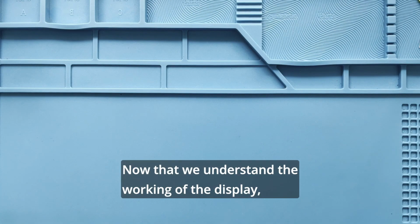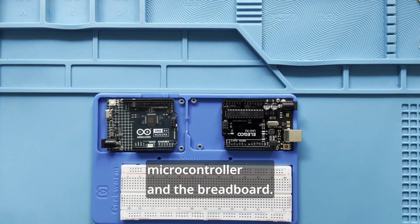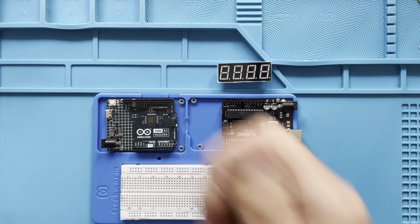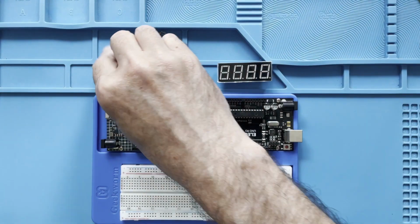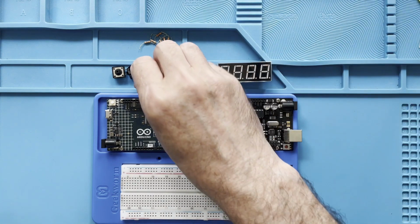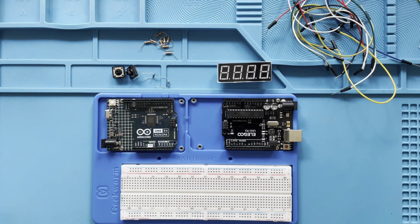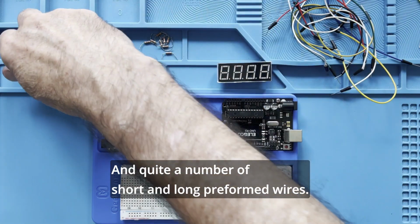Now that we understand the working of the display, let's distribute the components to our class. The microcontroller and the breadboard, the 7-segment 4-digit display, 8 resistors of 220 ohm, 2 push buttons, one will be the up button and the other the down button, 2 pull-up resistors of 10,000 ohm, 16 jumper cables, and quite a number of short and long preformed wires.